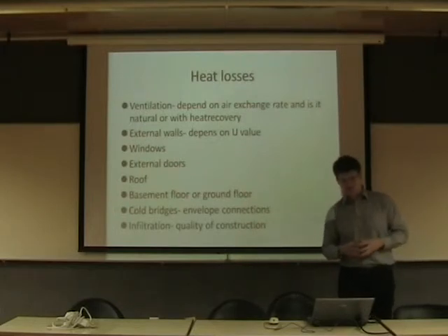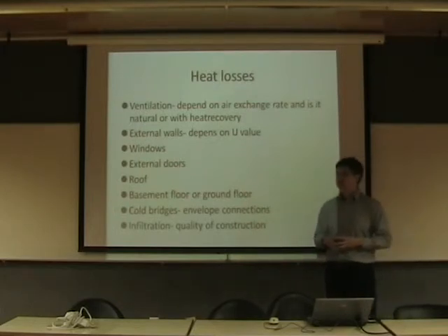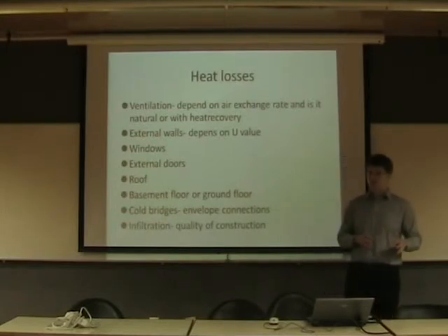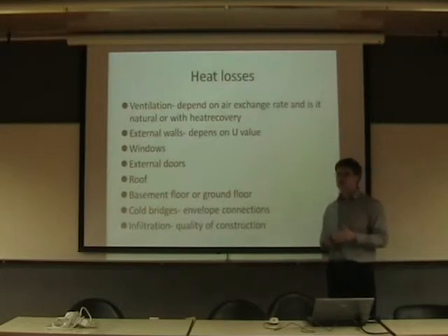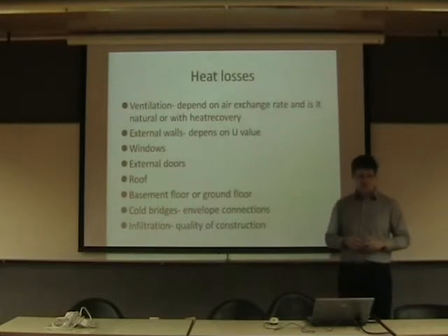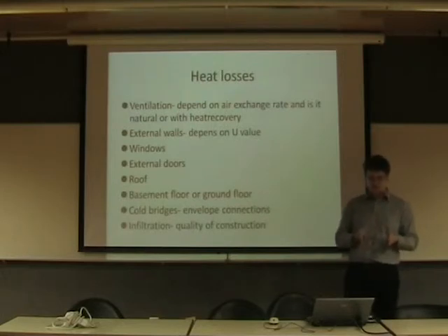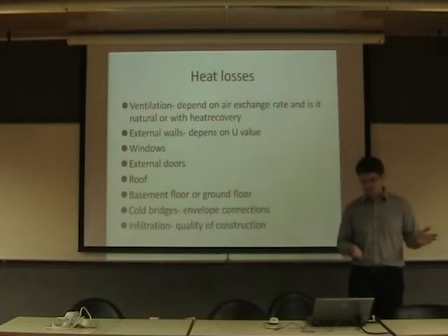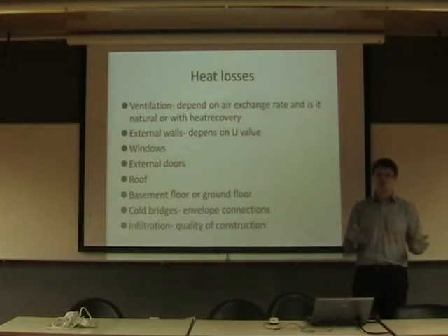It's a serious question. Also, the windows are the weak points of the house, because the old windows have single layer glass, like you have seen in Portugal, where they have lots of single glass, but in the Estonian climate we have 2-layer glass. Also in our own old apartment buildings we have this 2-layer glass, but the U value is about 3.0 or 2.7 something. With new glasses we can achieve about 0.75 or something.